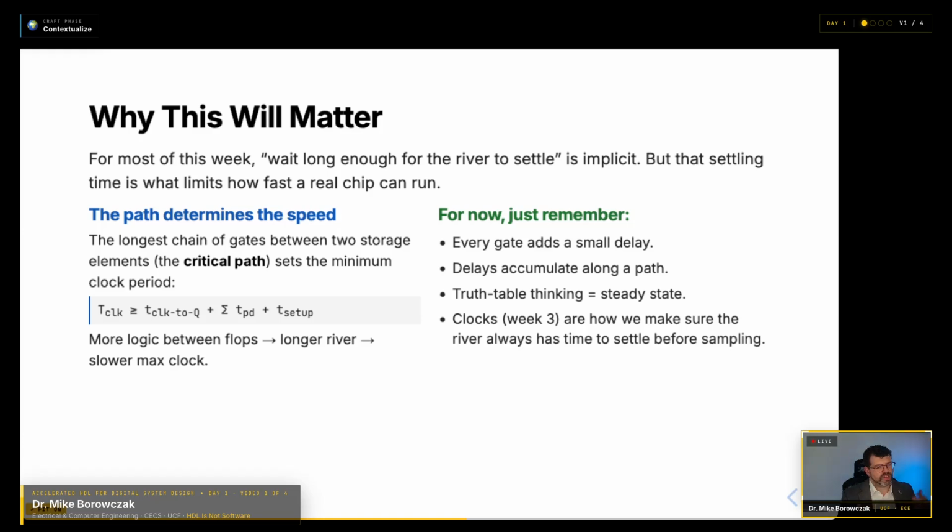Basically, the more things you want to do, the longer the total amount of delay, the total time it will take to get between all the inputs changing and your final output. And if you look across your entire design, the longest of these ends up creating what we call a critical path.